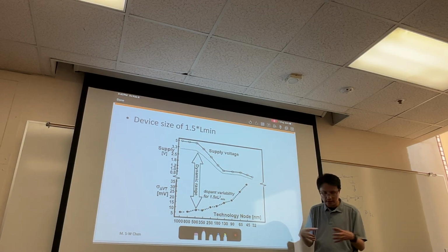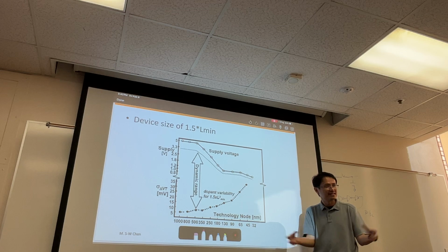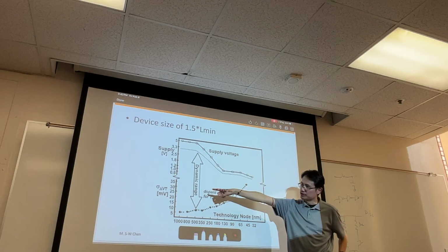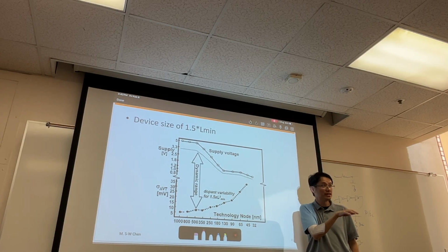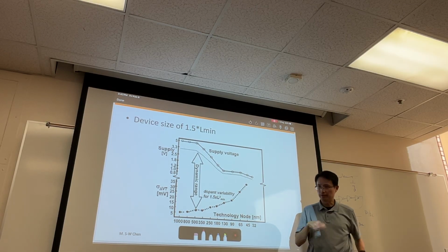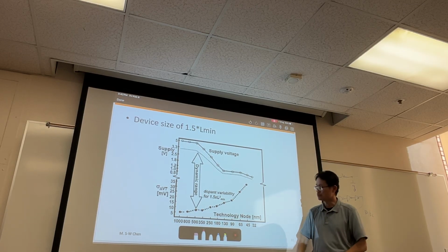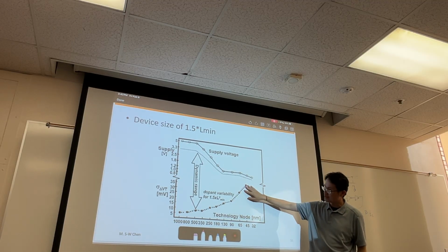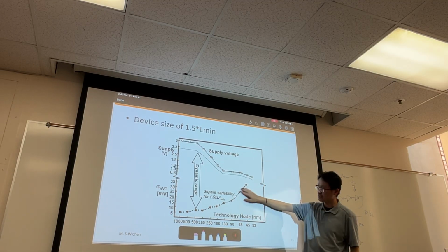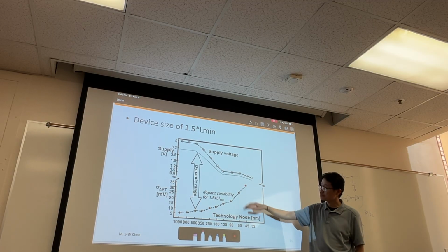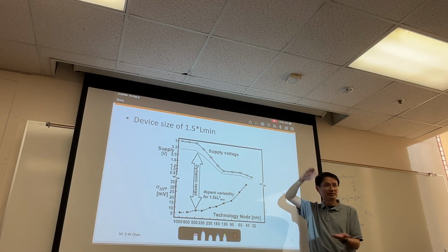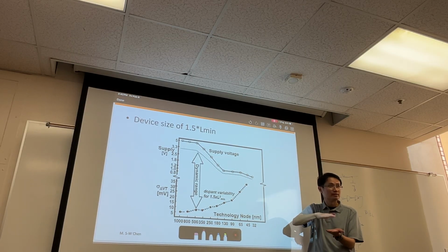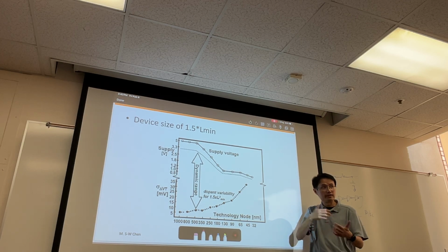However, as you go down, and if you assume that you shrink your analog circuit just like digital circuits, your threshold voltage variation will go up. Even though, as I said, A_VT also goes down, the square root of the area goes down even more, right? So you're going to have this trend. So this will be going up, right? So you see before maybe 5 millivolt, and now maybe 10 millivolt variation. You see this? You don't have too much headroom, right? Because your headroom keeps getting pressed down, but your variation is more and more.